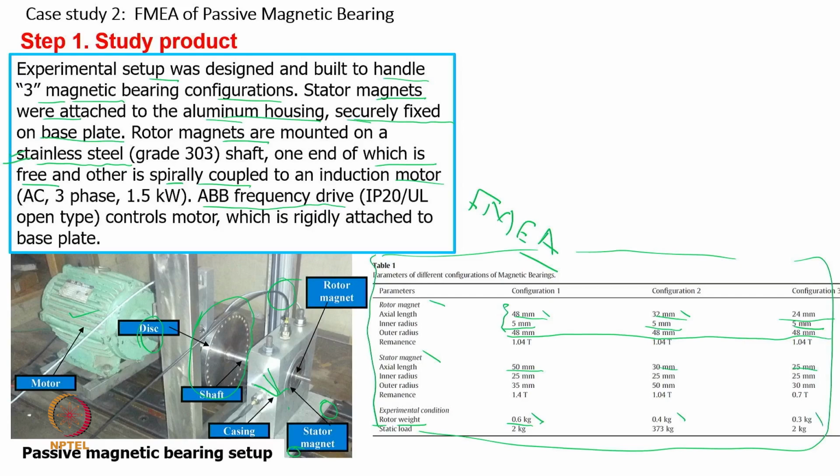So, these are the loads which have been shown, and in different configurations we applied the load in a different manner. Now, why have we kept the maximum load in configuration 2? Because the load carrying capacity in this case is very high. I can't go ahead with a low load carrying capacity. With a low applied load, the rotor will go and hit the outer bearing or maybe the housing surface, and that will be more problematic.